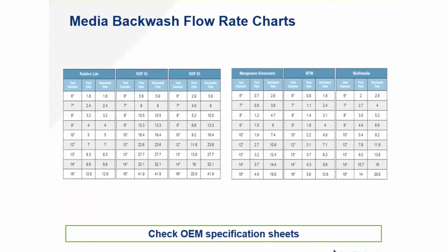If you're seeing your birm solidify or your zeolite solidify, you may need to adjust the backwash duration or the frequency. What's going on with that zeolite is we're using magnesium oxide to keep the pH of the water up as we precipitate iron and heavy metals out of the water by forming hydroxides, which causes the pH to drop inside the water.